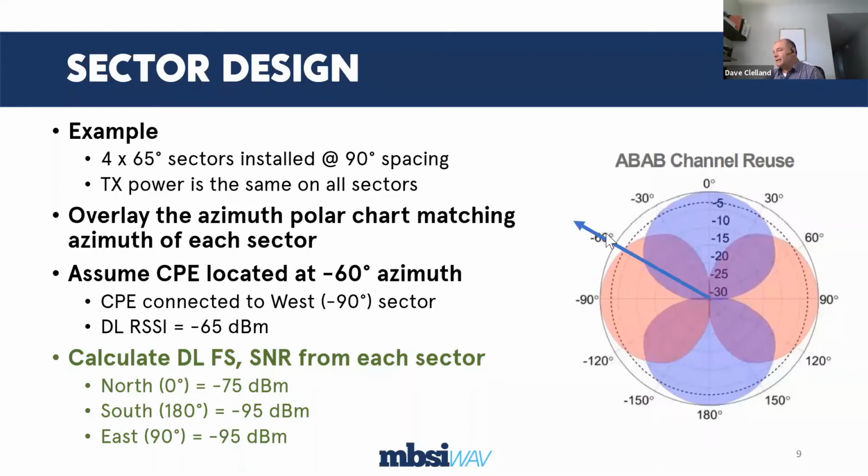I would expect that signal, if he were 1 kilometer away, and from our example on the previous slide, I would expect my signal strength to be at that point about a minus 63 or minus 64, something like that, because I am at the half power beam width of this western antenna. However,